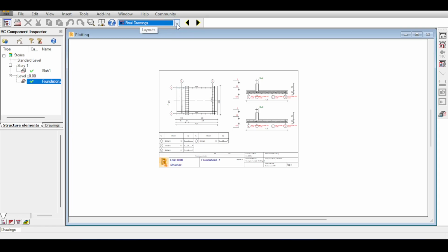Now, this is only one type of retaining wall. There are other types of retaining walls. For example, backbone retaining walls with abutments and stuff like that. There are retaining walls where the horizontal reinforcement becomes the main reinforcement, especially if you have abutments or columns that stiffen the retaining wall in the vertical direction. These are other topics I will cover in the future.